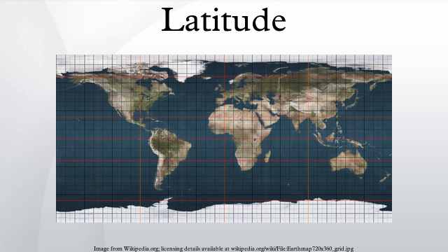longitude a two-dimensional coordinate system on that ellipsoid. To define the position of an arbitrary point, it is necessary to extend such a coordinate system into 3 dimensions. 3 latitudes are used in this way. The geodetic, geocentric and reduced latitudes are used in geodetic coordinates, spherical polar coordinates and ellipsoidal coordinates respectively.